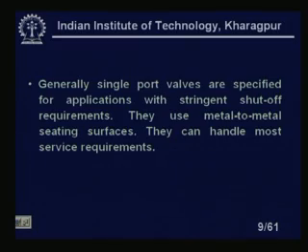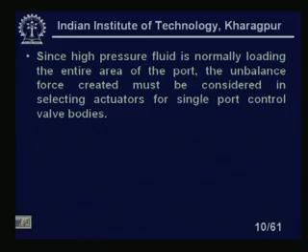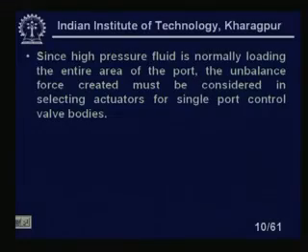They use a metal to metal seating surface and can handle most service requirements. Metal to metal means the seat is metal as well as the plug. Handling most service requirements means corrosive conditions and high temperature can be withstood. Though nowadays Teflon can also withstand high temperature, it is obviously not as high as metals like steel.